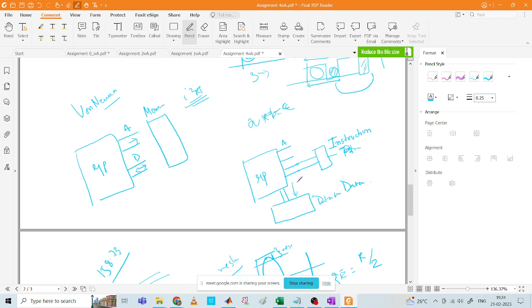Now while you are writing the value C into the data memory, parallelly you can fetch the next instruction also. So in one cycle you are storing the data and fetching the instruction. But in a von Neumann architecture, you take data A, take data B, you put back C, and then you fetch the next instruction. Everything happens over cycles, so there is no multi-processing in one cycle. But in Harvard architecture, you have multi-processing in one cycle, and that is the reason it is faster than von Neumann architecture.